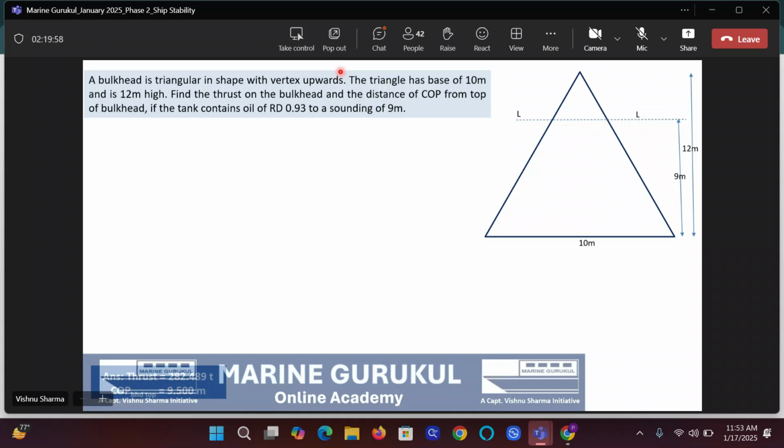Then it will become a combination of two shapes, both are triangle. You have just dealt with a combination of two shapes a while ago when you did a triangle and a rectangle. So what I'm suggesting is the simplest of all. Naturally, if tomorrow you come across somebody who has done it differently, don't bother. It can be done in different ways. Okay, this will be 3 meters. Now, guys, this is the immersed area X. Can you please calculate X for me first by similar triangles, guys?